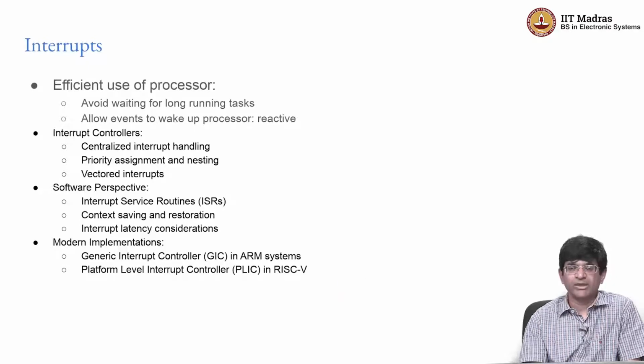So by the time one bit has been sent out on the UART, the processor would have managed to complete 10,000 clock cycles, right? So rather than waiting, what the processor would do is just dump some data into the buffer of the UART, go do some other work, and when the UART has finished transmitting the bytes that it needs to, it can send back an interrupt to say, okay, now I am free again, you can send more data if you want to, right?